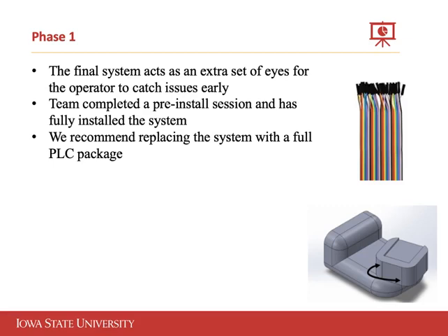We completed a pre-install to figure out the best way to do things and how to fix issues that we ran into during that. Then through 2 more sessions, we were able to get the rest of the sensors installed. For moving forward with Sukup, we recommend that they replace what is currently in the system with a PLC package, so that it'll be longer lasting. We also recommend that a professional team installs this so that it has the capability of being wired into the machine's automatic shutdown, so that when issues are detected, it will stop the machine, thus detecting issues quicker and stopping the issues from growing in magnitude.